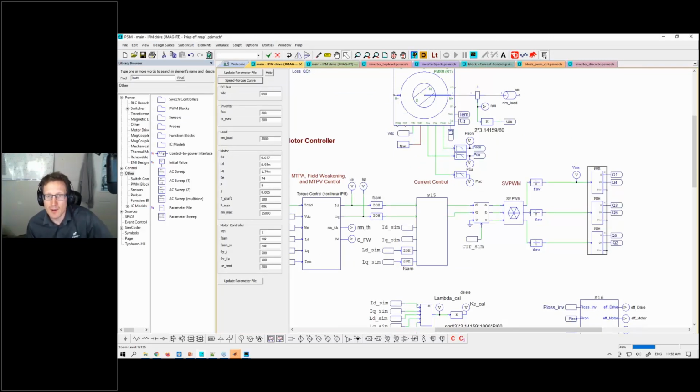Is there test software which validates versus actual tests? So PSIM has been around for about 25 years now, and many people have published papers with regards to accuracy. JMAG has been a well-used FEA tool, and many people have compared PSIM results and JMAG results versus real-world results. So there's lots of information out there if you wanted to look at accuracy.